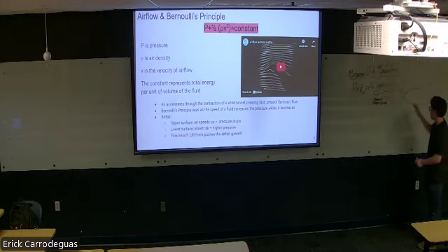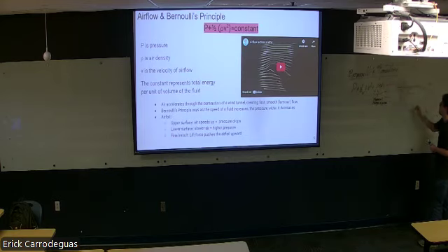As air hits the airfoil, let's say it has an angle of attack of 2.5 degrees, so it's a little bit more like this. Air starts traveling on the top of the airfoil, and as it travels on the top, it becomes faster. As air travels on the bottom, air slows down a bit.